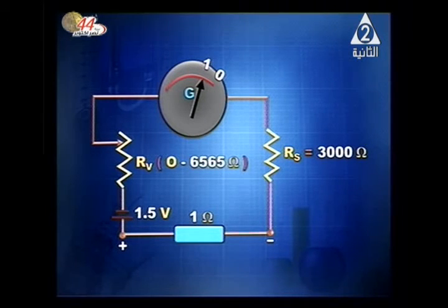Each time a known resistance is inserted between the test terminals, the pointer moves backwards to a position where the value of the resistance is written. We repeat with another resistance, for example, a 2 ohm resistor. It returns back once again, and the value of the resistance is written, and so on. In this way, the scale of the device is built up.